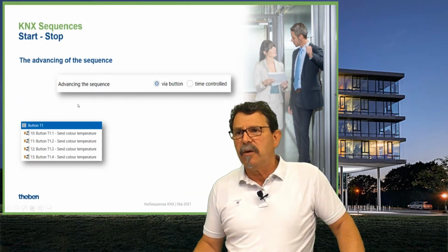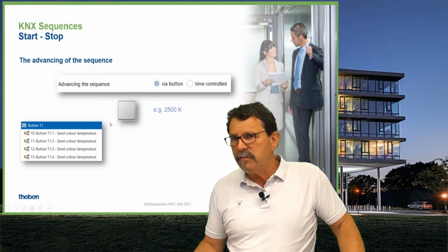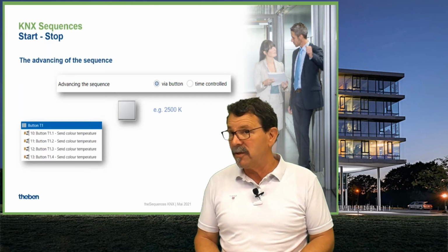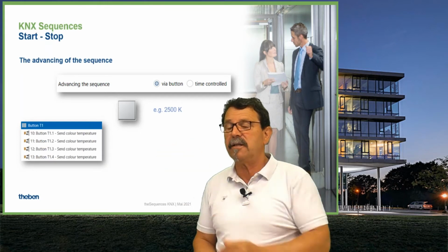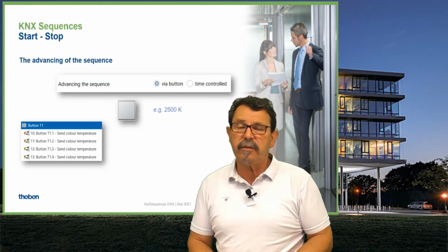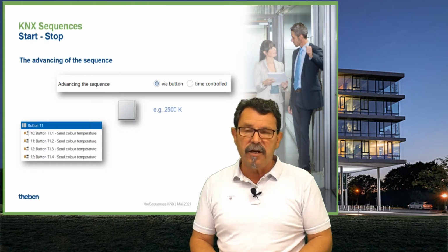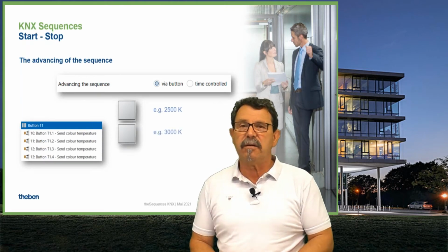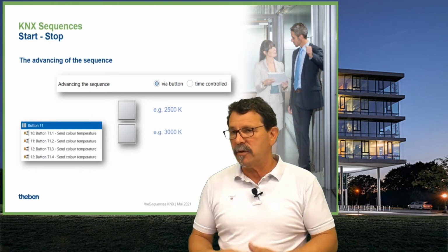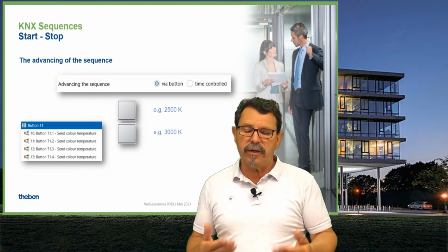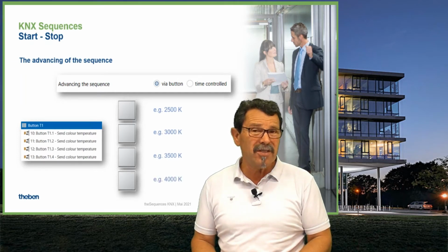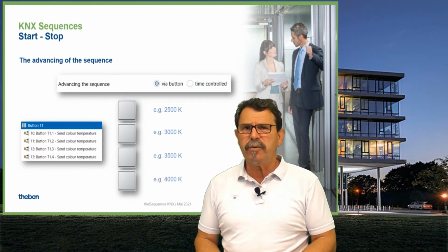However, we can send a color temperature. This can be used, for instance, for human-centric light. So you can address, like an example here, pressing the push button early morning, 2.5 K, we call up, let's say, the warm light color. Second push on the push button, we call up another value, and another value. So that means for HCL probably it is not that comfortable.